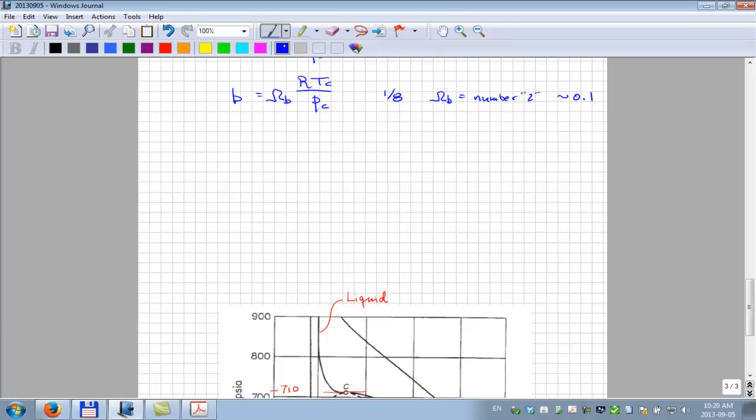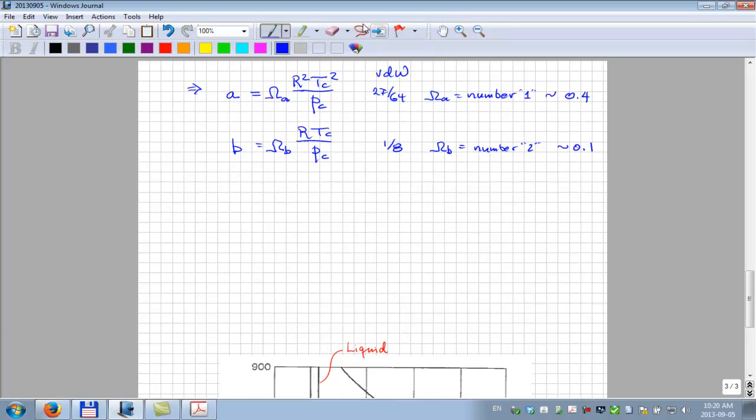One good question during the break was how do you calculate for mixtures? Do you calculate an average pseudocritical temperature and average pseudocritical pressure like we did for the Standing-Katz Z-factor method? The answer is not exactly, but we do calculate an average for a mixture. Let's say, as an example, we've got a mixture. I'll use this equation of state. It could be either a gas composition or an oil composition or a water composition.